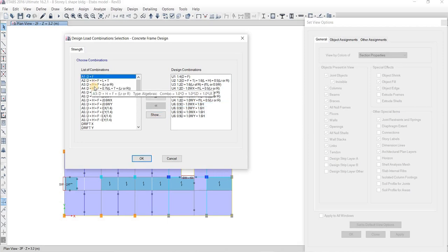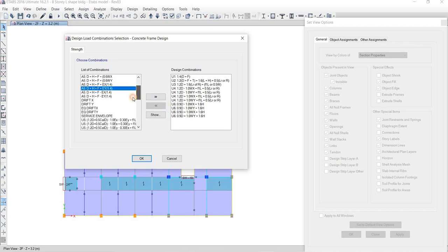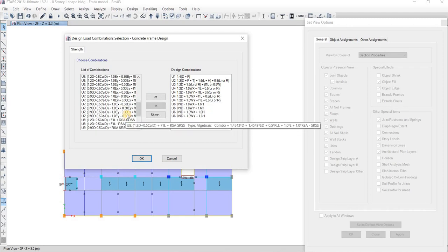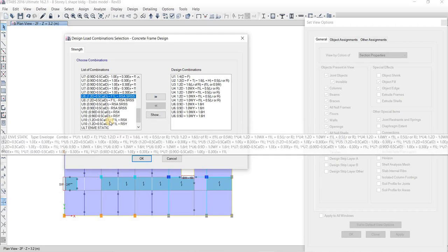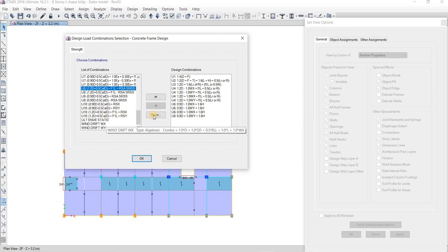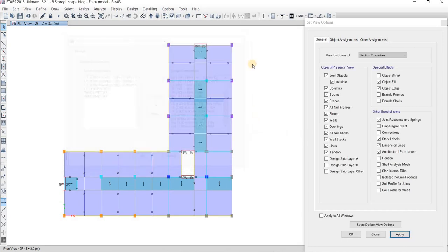So these other load combinations are for allowable. This is for the checking of pile reaction or number of piles. Okay. So we will leave the load combinations having static cases. Okay. So let's just click OK. Then I will just run this.